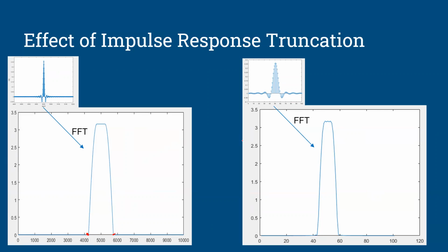And then if I truncate the impulse response and take the FFT, that's this one here. They look pretty similar, but you see there are some ripply bits at the top there. The transition from non-zero to 0 is a tiny bit different, but overall it looks pretty much the same. So if you're okay with your filter response looking like this, then it's perfectly acceptable to truncate your root raised cosine filter. And in practice, this will work pretty well.